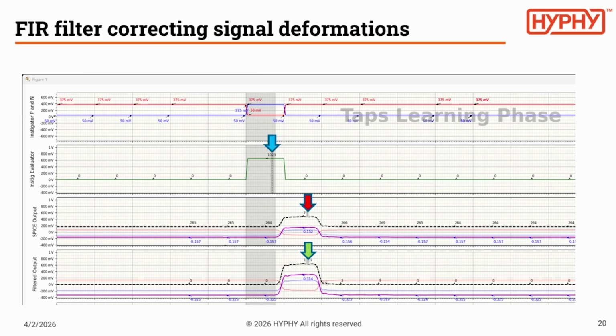And make sure that the correct value is at the moment where the gray sampling bar is drawn in. At that same point, we need to be sure it has the correct value. We don't care what the other values do and how the pulse shape changes over time, as long as the value at the exact sampling time is correct. And we can prove that that is correctly implemented in the FIR filter.